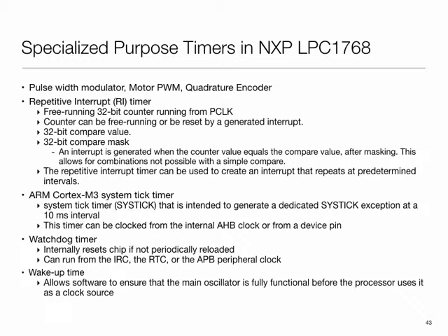That example of the Mars Pathfinder that I described is exactly what was happening there: the high priority task was not getting to run because of the priority inversion, and therefore it was not able to reach the part of the code where the watchdog timer was disabled. So we start and we stop, and the watchdog timer has to be stopped. Because it was not stopped, the whole system had to restart, which is what we wanted because there was a problem happening. So you want to restart the system. Watchdog timers are pretty desirable to have, as something of a last resort to guard against something bad happening.